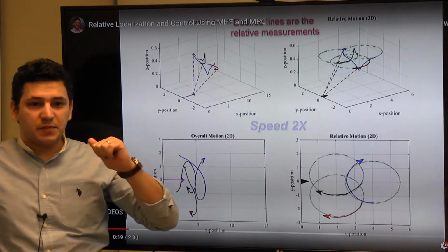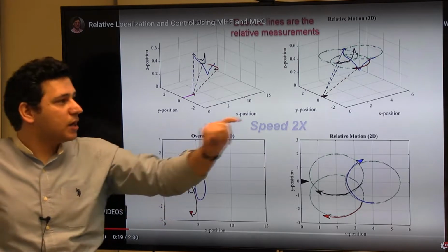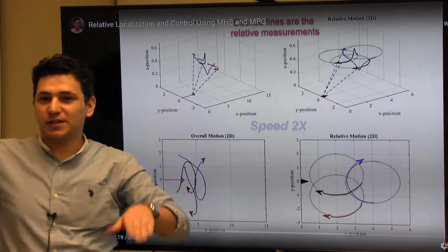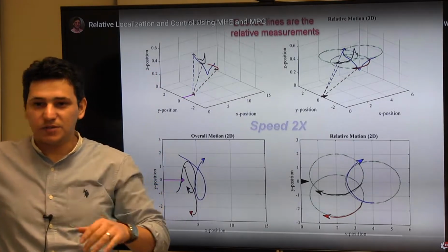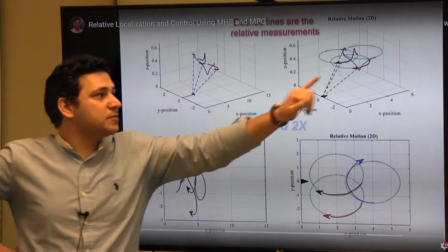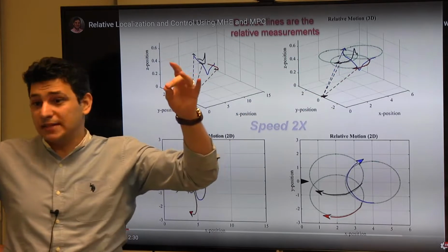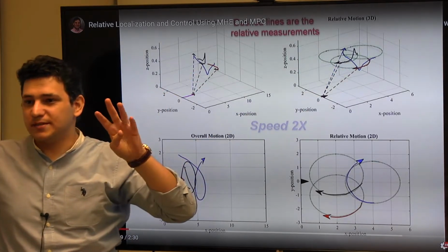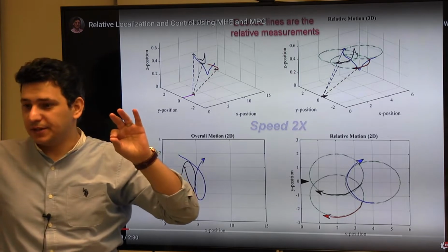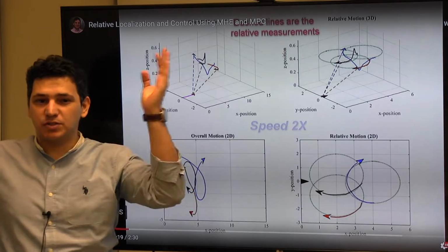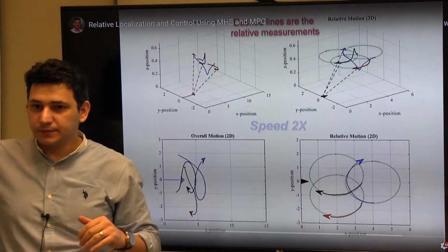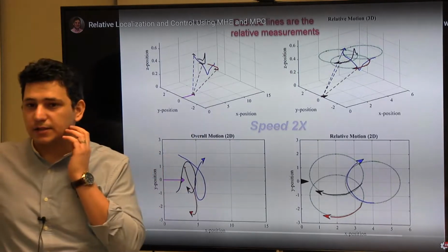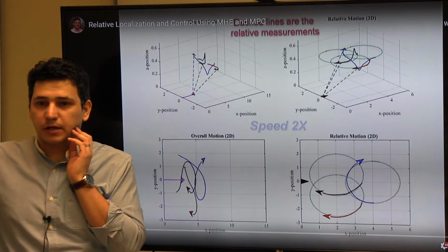We do the control using MPC, and what we measure are basically the range and the two bearings, the horizontal and the vertical bearing, to find an estimate for the robot position x, y, z, and theta, or phi. So here we have 4 states, x, y, z, and phi, right? And we have 3 measurements, range and 2 angles. Are they holonomic or non-holonomic? Non-holonomic in this case, yeah. These robots were non-holonomic, right?